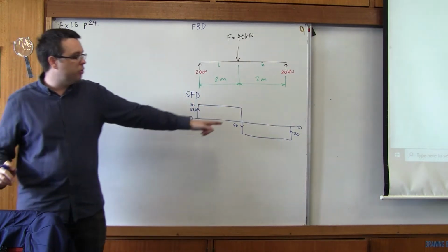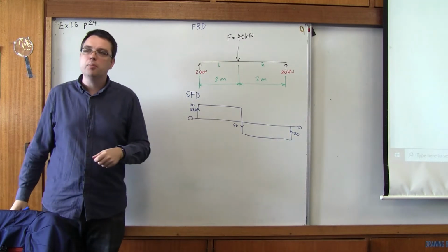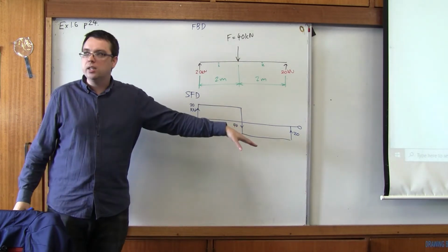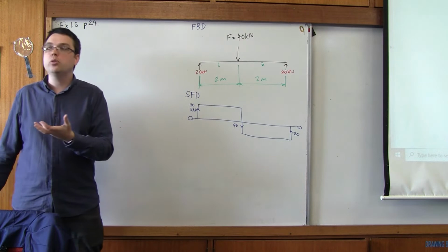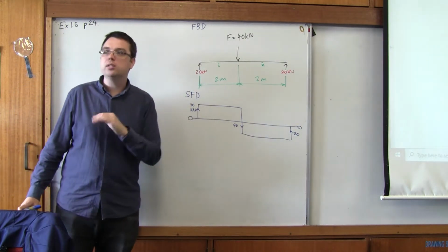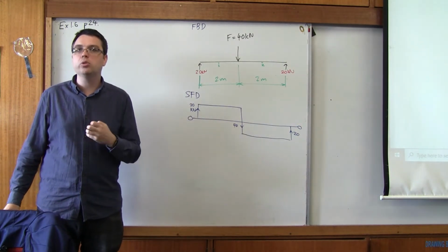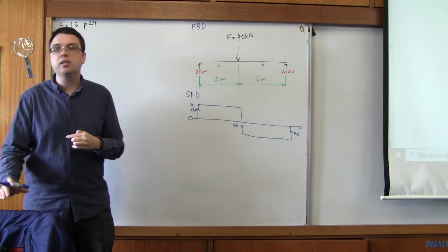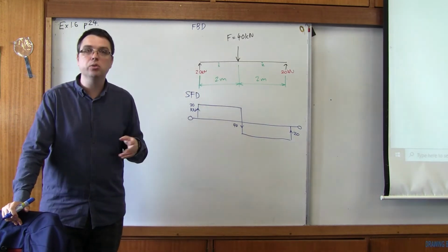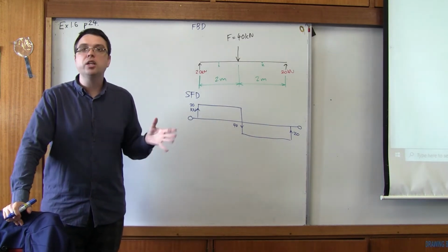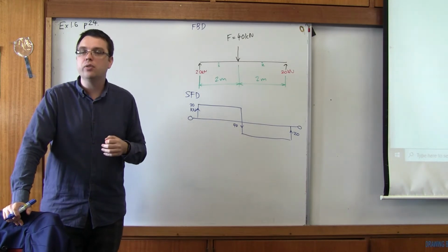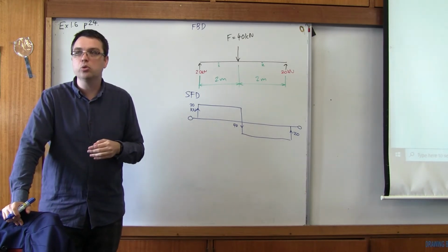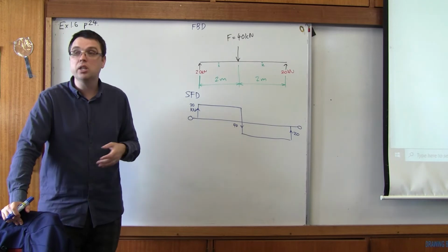Right? You might say that there's a 40 there. It's like, no, doesn't matter. Because the maximum quantity, right, it doesn't matter if we use absolute values, right, 20. 20 is the maximum shear that we're going to do. That's what we will design our beam for. We'll say, hey, just checking, I know shear is not usually the critical value, but in this case, do we have enough, is it strong enough to support 20 kilonewtons? And we say, yeah, it can.